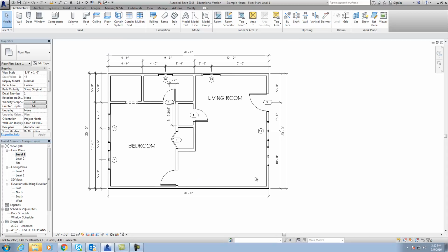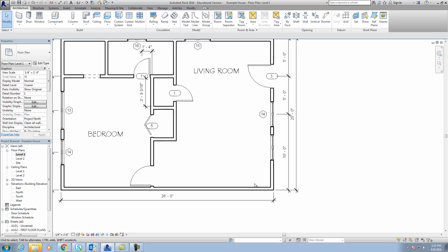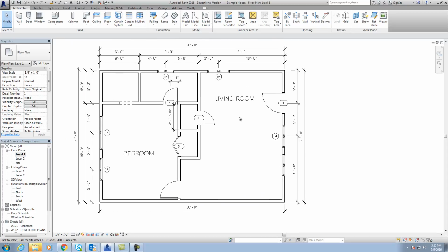First thing we'll do is start making a kitchen here. Now this is just a small little cottage or cabin, and it's got a living room here. This is going to be the kitchen area down here. I want to do an L-shaped kitchen. And inside that L shape, we'll have a kitchen table, and we'll go from there. But I want to show you how to start this. First thing I always like to do is start our base cabinets. And remember, base cabinets or any cabinetry in a kitchen, they're made in 3-inch increments in your width.